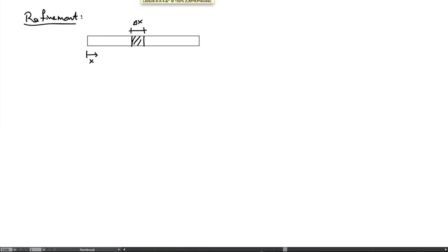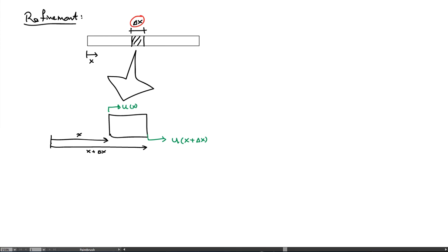Now, let's look at just one small refinement of the concept of strain. So we have this definition, which is delta L over L for strain, and it gives an average definition of strain. But let me consider a bar of material, and let me examine just a small piece of the bar. So it has some length delta x, and it's located someplace along the length of the bar. If I examine this little chunk of material and think about the bar deforming, then the material on the left end will have a deformation, and let me just call that u of x.